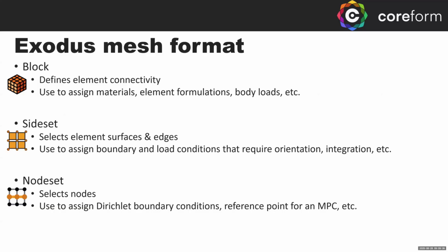And then just a high-level overview of the Exodus mesh format, specifically those data types. There's this idea of a block, which is a set that is primarily used by most solvers to assign materials or element formulations to. You might want to apply a body load. While we show an icon of a volume, if you're doing a shell analysis, a block can also be assigned to a surface, but it's really about where I want to assign some sort of material formulations. It defines the overall element connectivity.